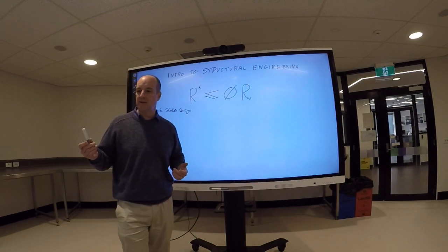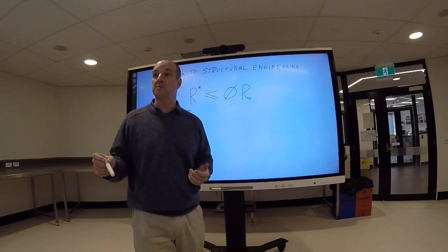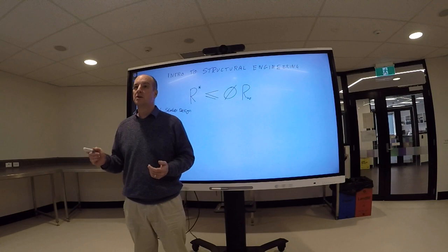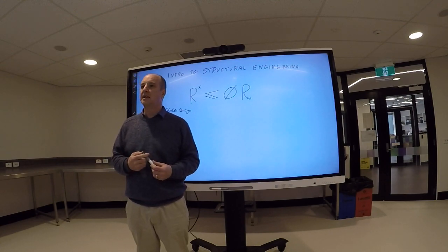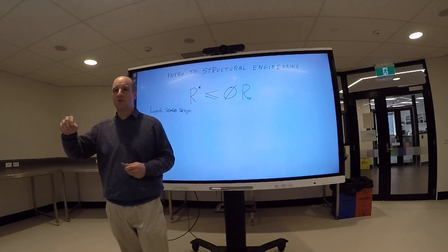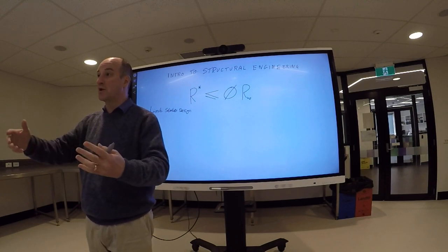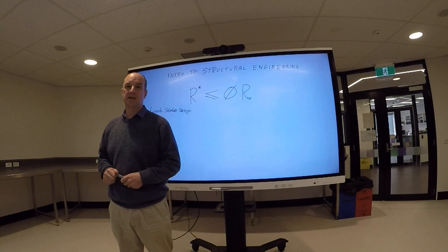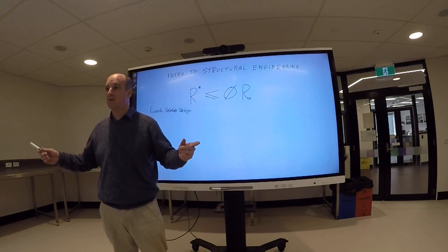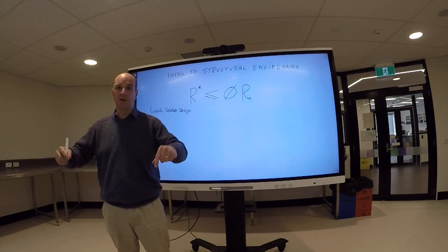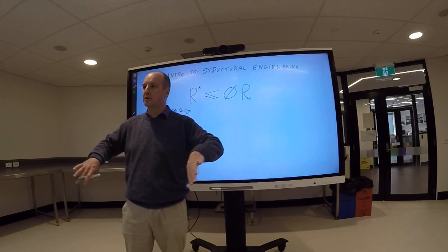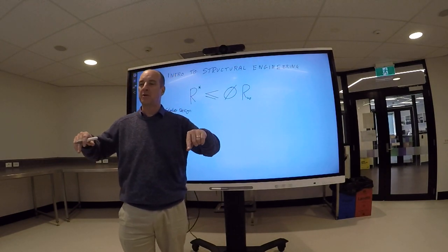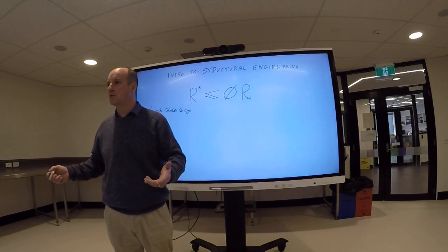Another limit, a common one, is called serviceability, okay? Serviceability is about the ability of the structure or thing to do what it's supposed to do. So for example, if we have a beam and we put a load on it, it will bend a lot and not break, but if it bends too much, it can't really do what it's supposed to do.